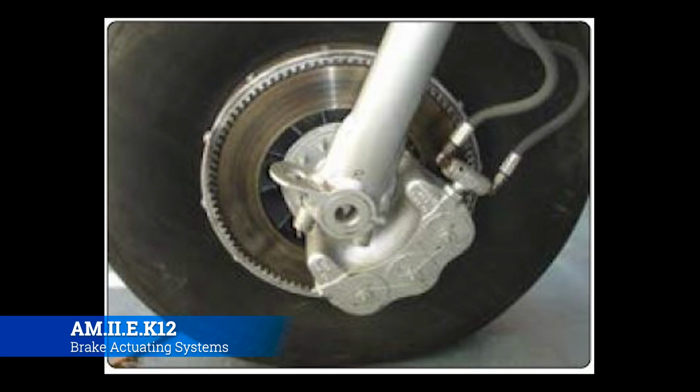Okay, so each cylinder accepts the actuating piston assembly comprised mainly of a piston, a return spring, and an automatic adjusting pin. Each brake assembly has 6 brake linings or pucks. 3 are located on the ends of the piston, which are on the outboard side of the caliper. They are designed to move in and out with the pistons and apply pressure to the outboard side of the disc. 3 more linings are located on the opposite side of these pucks, and on the inboard side of the caliper, these linings are stationary.